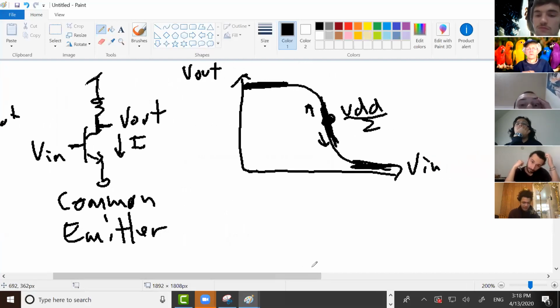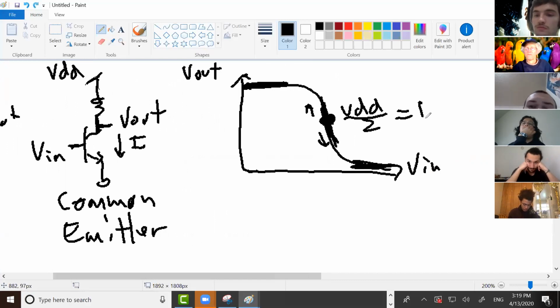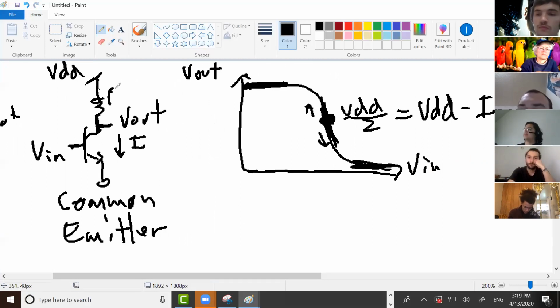Let's say you're targeting your default current to set Vout at VDD over 2. You also know that Vout is VDD minus I times R. Do you agree with that?